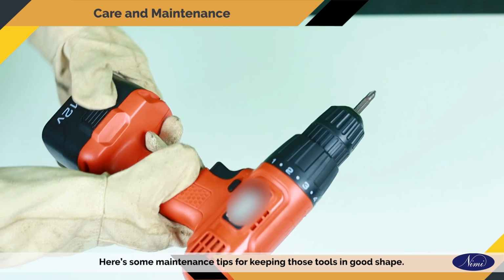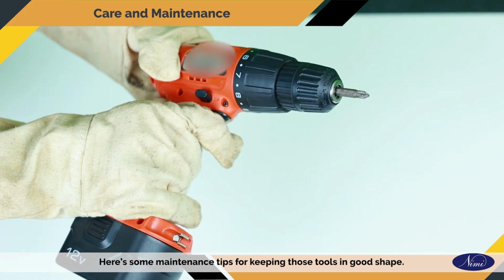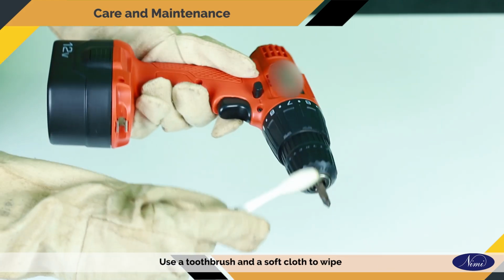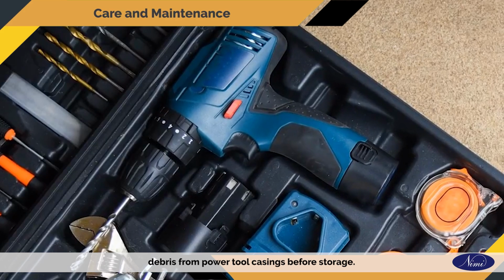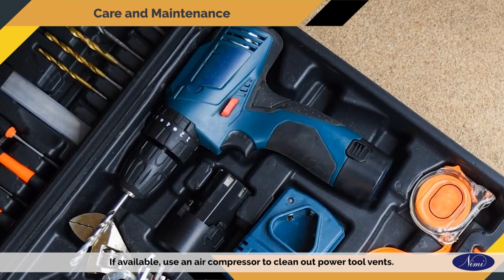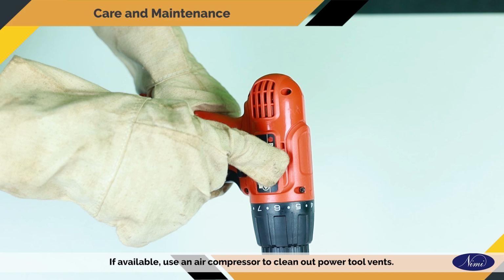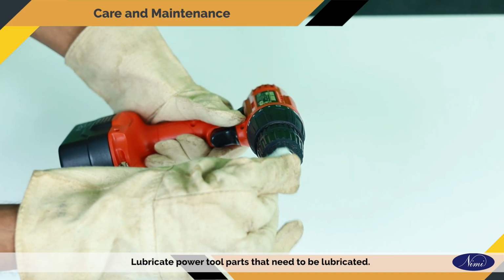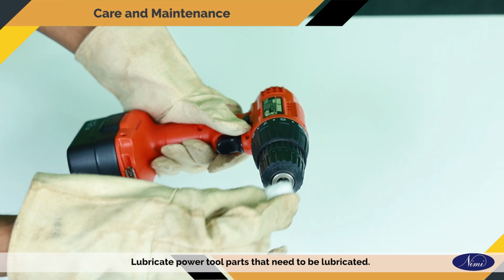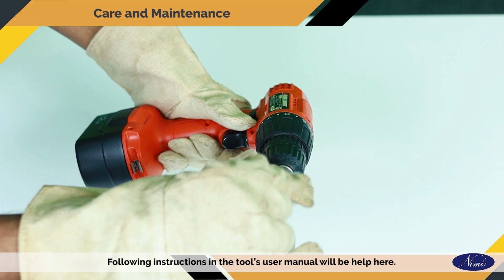Here are some maintenance tips for keeping those tools in good shape. Use a toothbrush and a soft cloth to wipe debris from power tool casings before storage. If available, use an air compressor to clean out power tool vents. Lubricate power tool parts that need to be lubricated. Following instructions in the tool's user manual will help here.